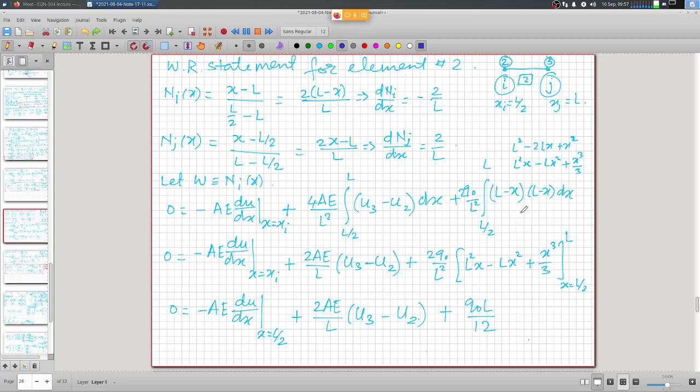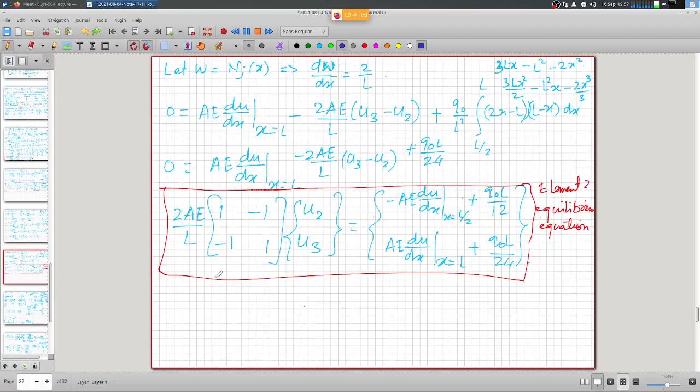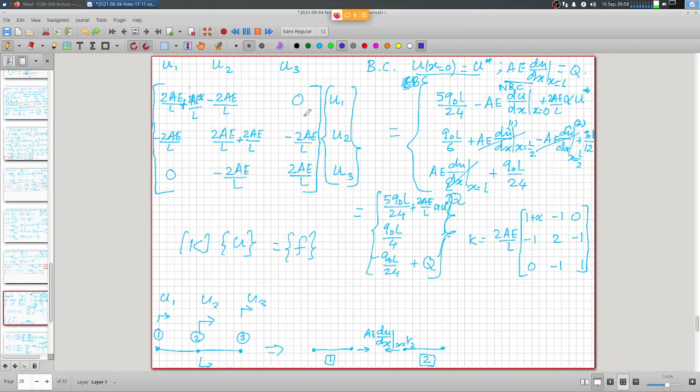So you impose the condition that the amount of work done should be same, and then you define the equivalent nodal values of forces, and once you have that, then it's just this algebraic equation, and every element will result into this kind of set of algebraic equations for each element. So what is done in finite element software is generate these kind of element level equations for one element, then assemble it into the global assembly. So just as we did for element number 1, we populated the terms corresponding to degrees of freedom 1 and 2. And then we moved to element number 2, populated the terms corresponding to degrees of freedom from element number 2, and so on. And after the complete assembly, we look at these terms and impose the boundary conditions